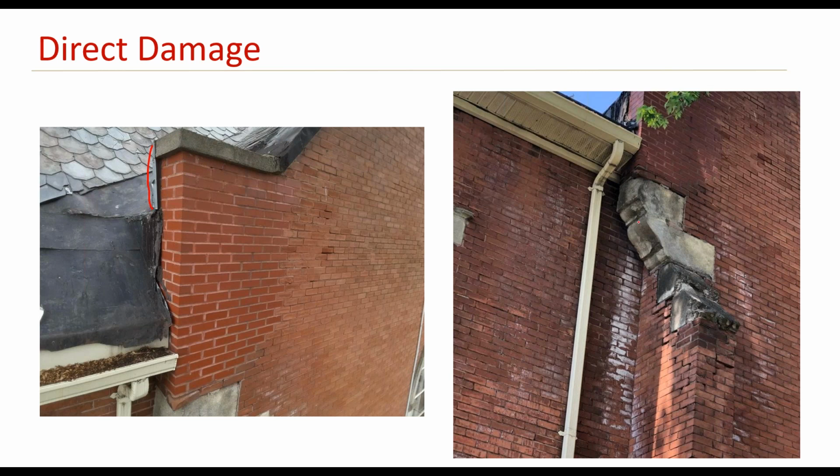I do not have the full image with me now, but here the person who did the repair for this part just decided to stop it here. This parapet should have had a little bit of height at this location, so that it prevents the water from overflowing it. Unfortunately, I had a full image where the other side of the exterior wall was not repaired, so the original state was there, and this parapet was higher. The original parapet was higher than this one. So, hope this answered the question.